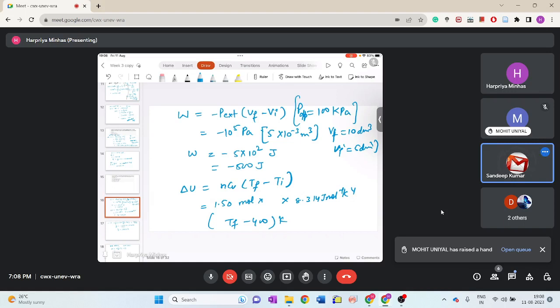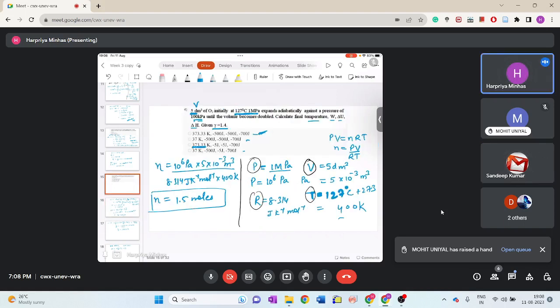What are the options for temperature? Because when we are adding minus 16 to 400, it will definitely not be 373. It will be 383, I guess. It may happen that they have given the answer based on the monatomic assumption, but here gamma is 1.4. Yes, maybe. That's why the solution is considering the monatomic value, not this value.